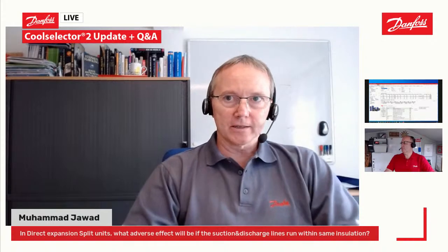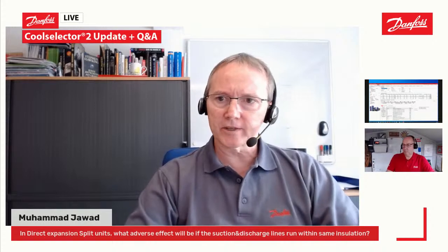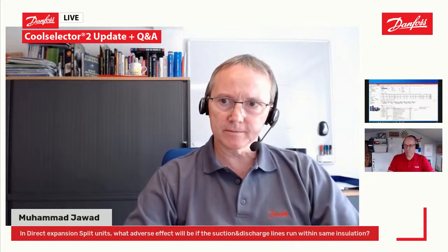And depending on this temperature relation, you get to a point that under these circumstances, a superheat value of this little is possible. Under different circumstances, a superheat value of that much is required to protect the compressor against leakage. So this is quite different, and there is no one value like the superheat ratio I can give you for this air conditioning system setup. This depends on the ambient condition the system is actually running at.